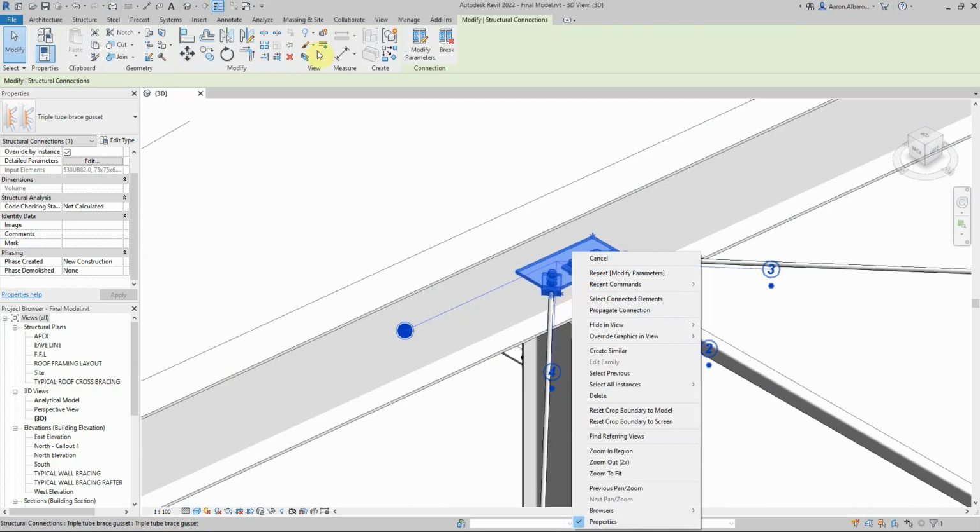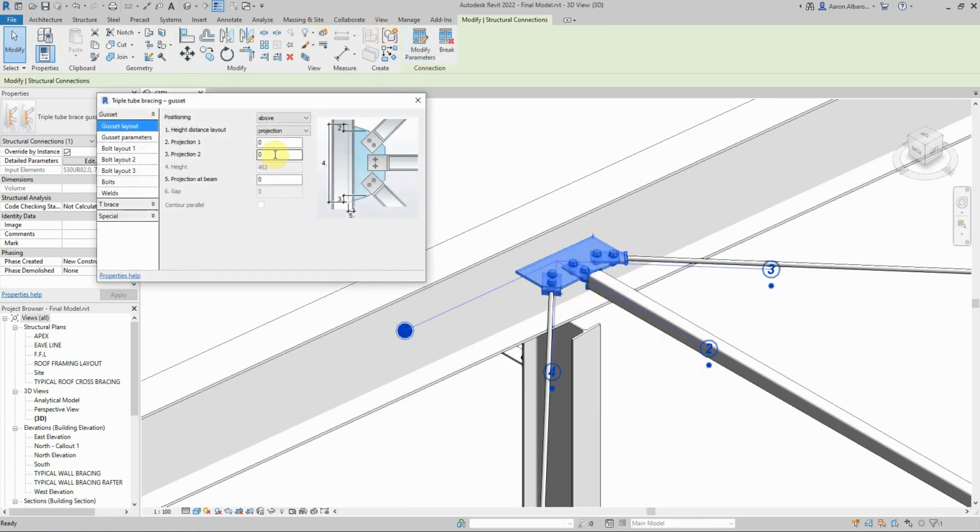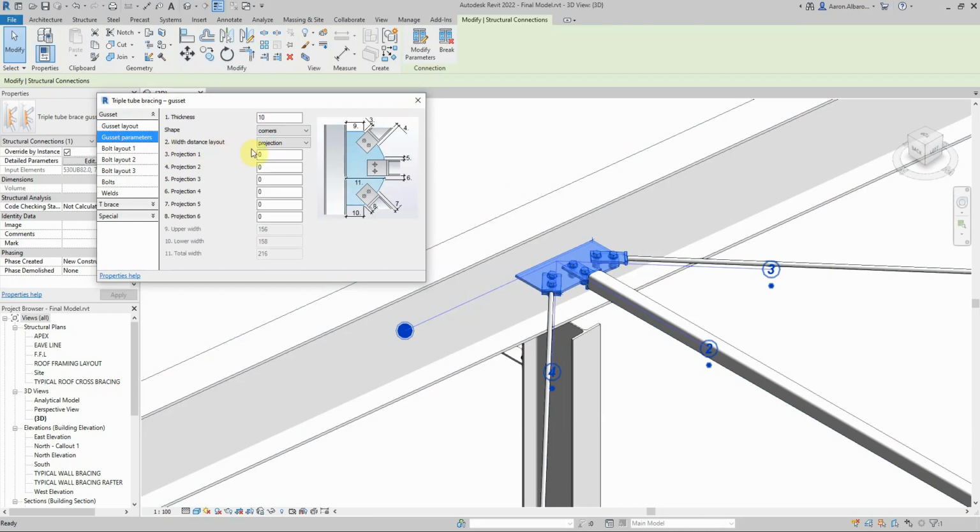By the way, we can do one last change with that by making the gusset plate sit from below rather than above, so you can see that connection. And on the gusset here, I usually give it a small distance, 5mm only on each side, to make it